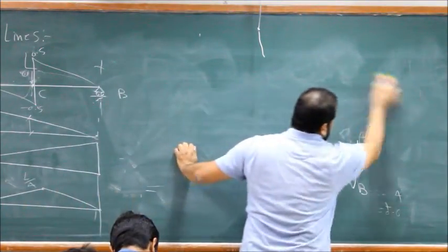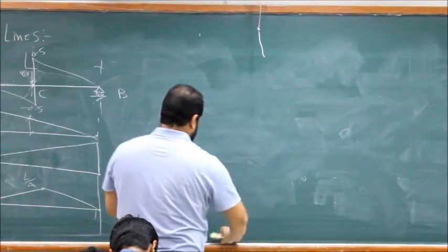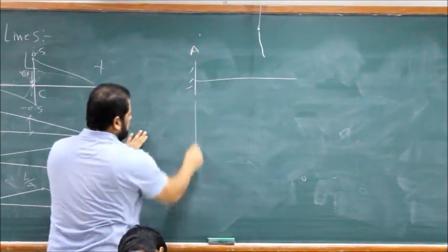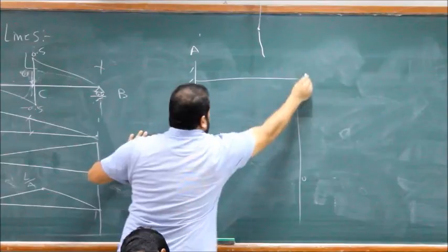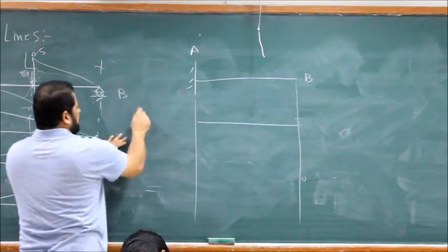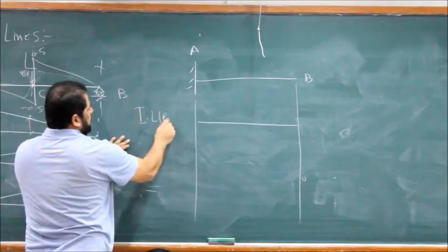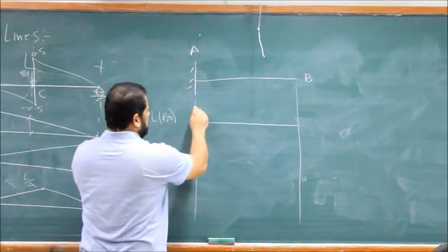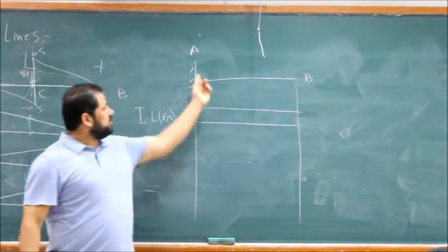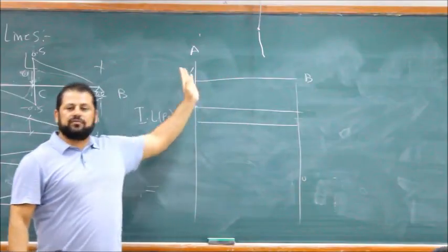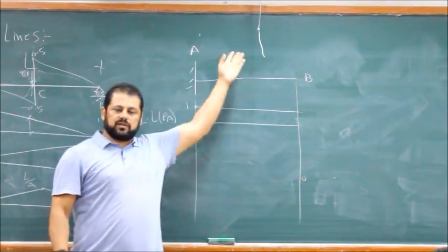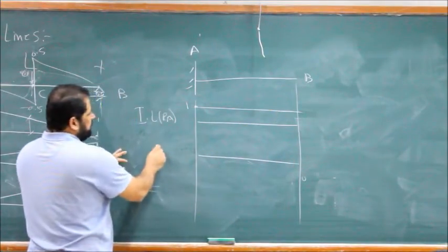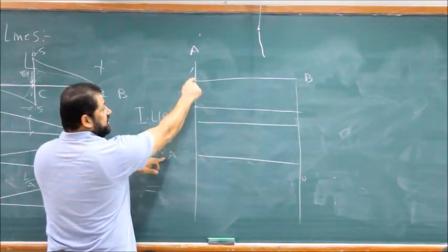Cantilever is the easiest. You have a cantilever beam. Influence line for the reaction at A, IL RA: 1 upward, all the time. When the unit load is here it is 1, and when the unit load is here it is the same. It's the only force for reaction in the y direction, so it always equals the force. So 1 all the way. How about VA? Shear here.